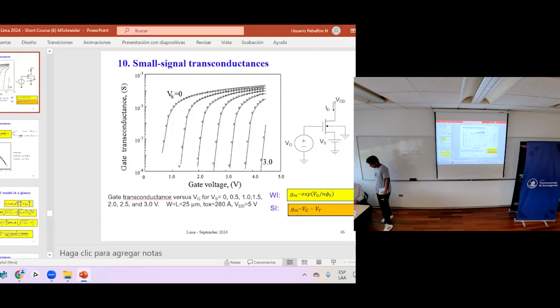What you need is what we call a centroid structure. You have a common center of the transistor. This is not so simple in some situations, but you try to do this. This is what we call centroid. So you have, say, a geometrical centroid or a center of mass, but you have to split the transistor. But in general, you do this because you want matching.